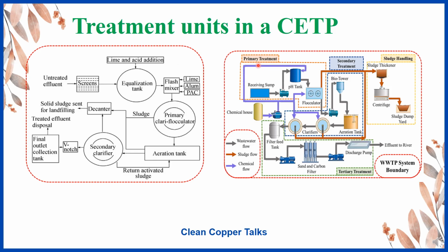A thumb rule says 60 to 70% of inorganic solids is removed in primary treatment, and 20 to 30% of BOD is also removed in primary treatment. But this is a general thumb rule. It varies a lot from CETP to CETP based on the type of partner industries in that CETP. There can be cases where the partner industries produce a lot of toxic waste or chemical waste, then BOD removal might not happen because BOD might not be there. There can be COD.